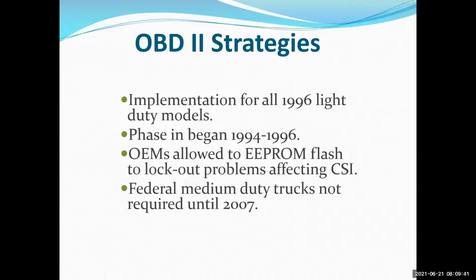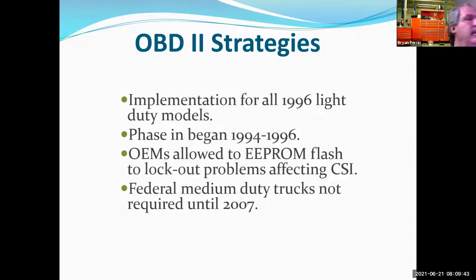Keep in mind that these vehicles, 96 and newer, whether they're OBD2 certified or not, will still have that 16-pin diagnostic link connector. And that's why I make the distinction that that's a 16-pin diagnostic link connector and not an OBD2 connector, because there's plenty of vehicles that are not OBD2 certified that have that 16-pin diagnostic link connector. So one is the connector that we're going to hook the scan tool up to talk to it. The other is the programming and the rules that the computer system on the vehicle has to follow. Two different things.